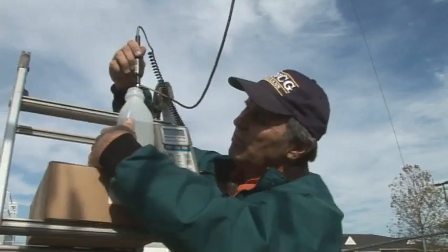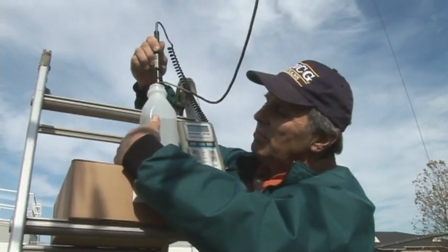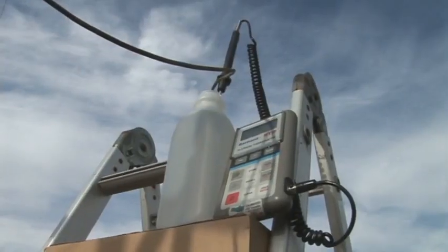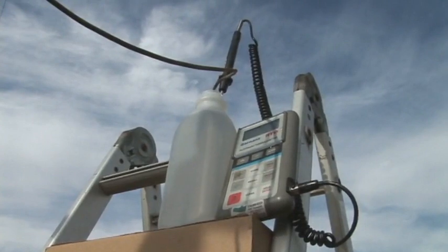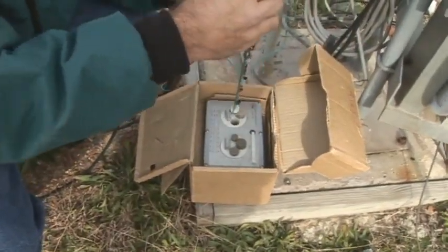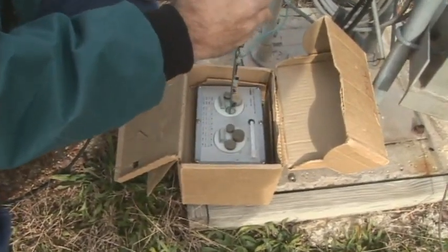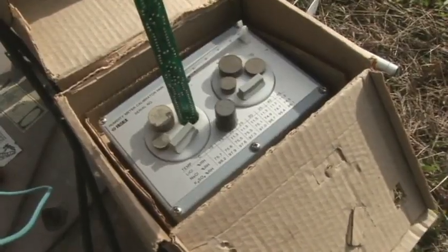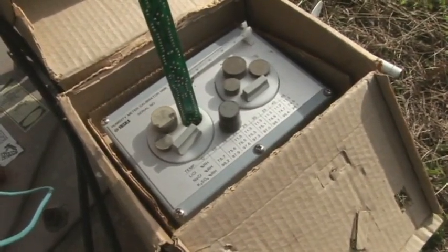For temperature and humidity sensors, this means imitating the temperature or recording of the humidity and temperature with a separate sensor. In this instance, the temperature sensor will be calibrated using 3 water baths. The probe will be immersed in the baths and a traceable sensor will measure the temperature of that bath. The RH or relative humidity sensor will be immersed in the salt solutions that have a known relative humidity. The values will be read and referenced to the RH of that solution.